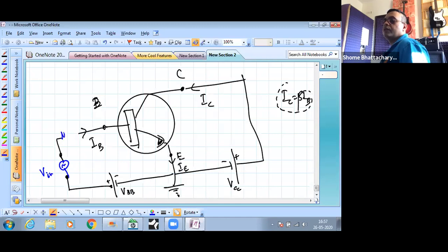Okay. And we have connected some kind of input resistance which can be controlled or which can be connected such that it gives us some advantage. It gives us some parameters of what we expect. Whereas here on this side, across the collector emitter junction, we connect the load resistance. This is the load for the circuit. So whatever voltage is across the load resistance, that becomes our output. So this becomes our output terminal, and this becomes our input terminal.